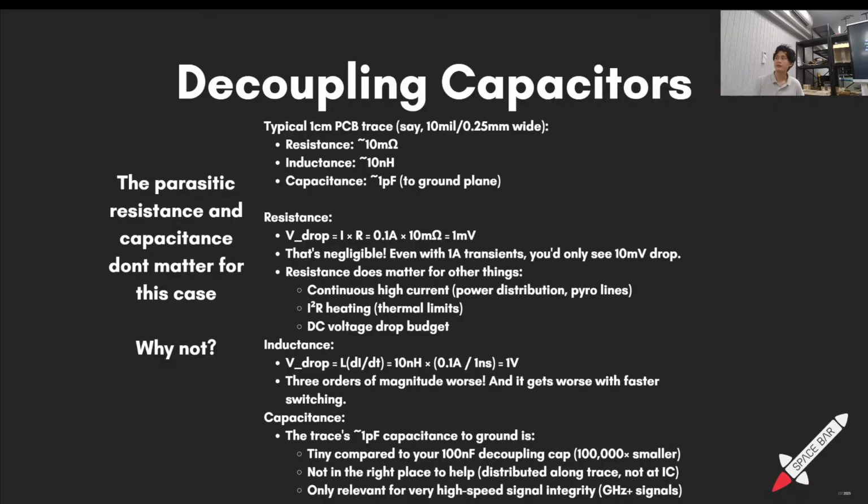Is it very small? Yeah. The capacitance is supposed to resist changes in voltage, but since it's very spaced out, it doesn't really affect each other. It's not that it's spaced apart necessarily, because in reality it's a bunch of infinitely small capacitors, infinitely close together, and you integrate across the whole thing. So it's uniform. And not only that, most of it is very far away from the chip, so most of it does not contribute to decoupling much.